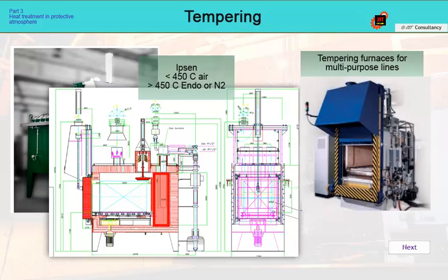Heating elements, electric or gas, as in retort furnaces, are placed outside the work area, where they heat the protective atmosphere, and this heat is then transferred to the working chamber and to the batch by a fan. Since the furnace lining is usually oxidation resistant, these furnaces can be kept at a permanent temperature even without a protective atmosphere. The batch is usually placed in a heated furnace.